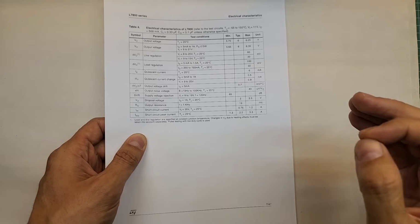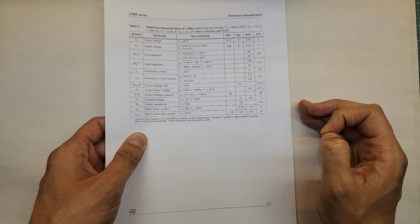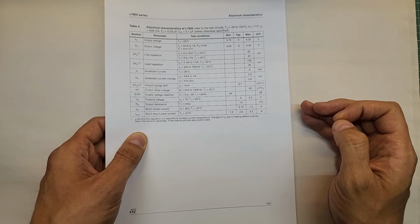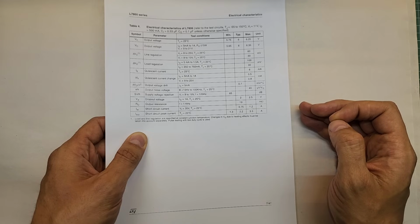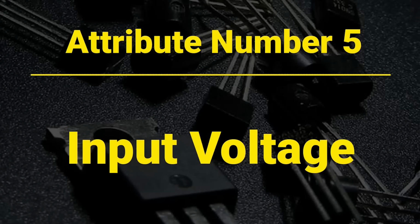For example, if you are using L7805 to create 5 volts, you have to apply 7.5 volts or more to the input terminal to make sure that the device will work as it should. There is another attribute that indicates the maximum input voltage. Attribute number 5, input voltage.